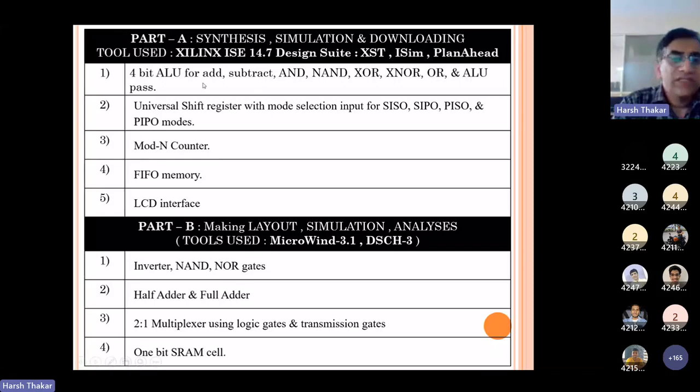In your second year, you have studied this term PLD, that is programmable logic device. So PLDs are classified as simple PLDs, SPLDs, and high density PLDs. Simple PLDs are classified as PLAs, PALs, and PROMs, similarly, high density PLDs are classified as CPLDs and FPGAs, where CPLD stands for complex programmable logic device, while FPGA stands for field programmable gate array. So the company Xilinx, which pioneered in manufacturing FPGAs, also made what is called a synthesis tool.